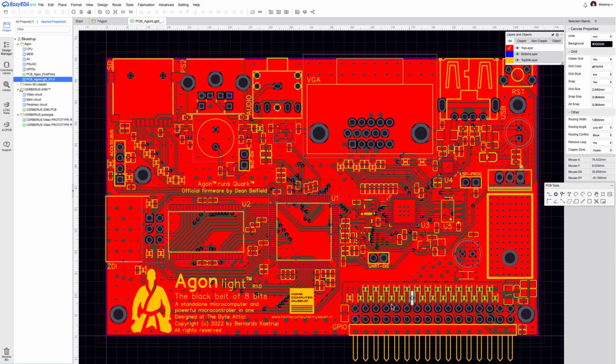And the final thing is you want the TVS diodes to be very close to the points that are exposed. So if this TVS diode here is protecting this pin, you want it to be physically close to the pin it's protecting and not on the other side of the board, because otherwise an electrostatic discharge on this pin will cause damage before it gets to the diode. So little things like this. So this is pretty much it.